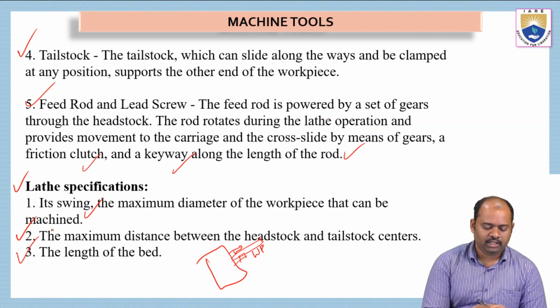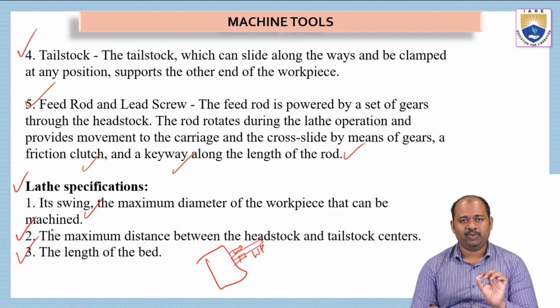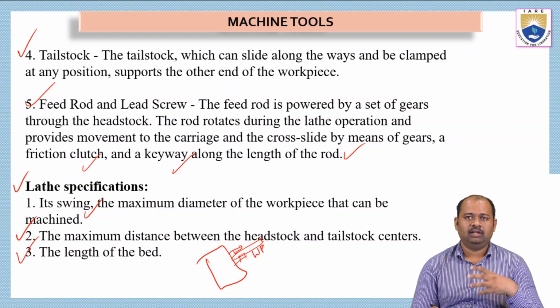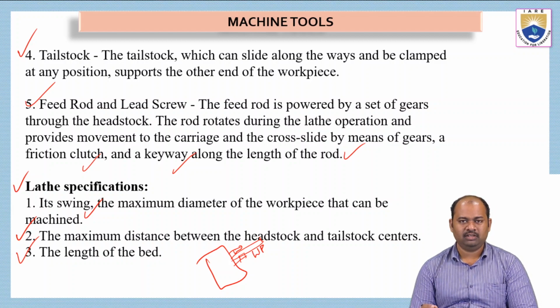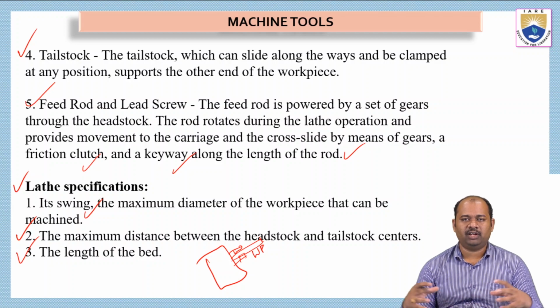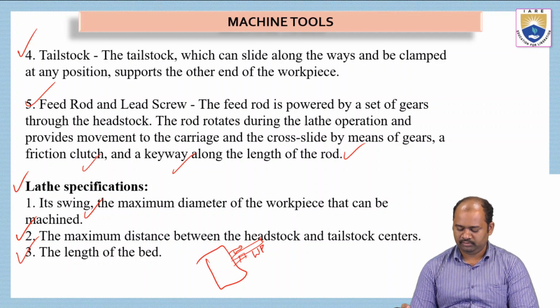And then the length of the bed. The length of the bed also plays an important role when we are selecting a lathe machine for a particular machining operation, because if the length of the bed is smaller than the workpiece, we cannot machine it.